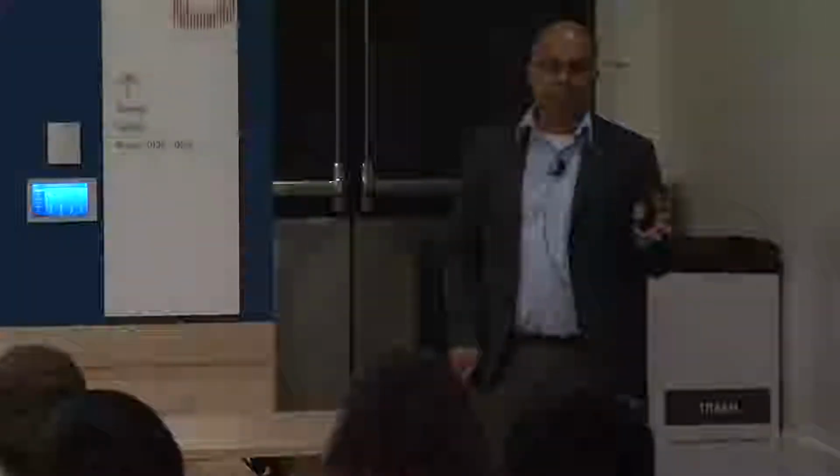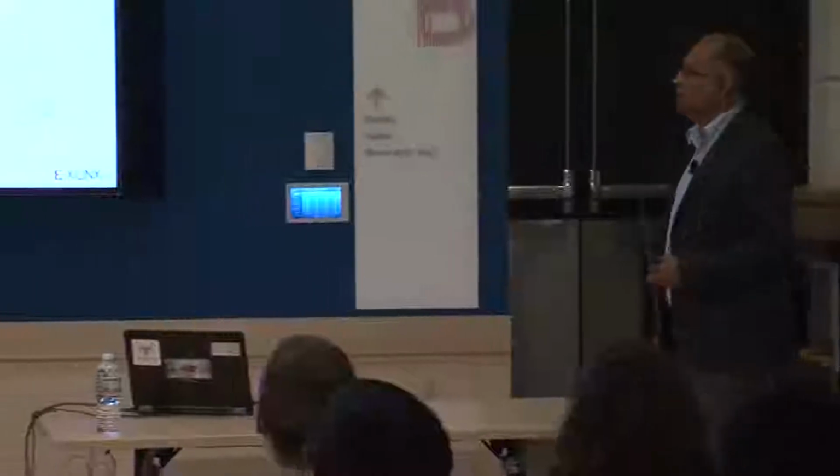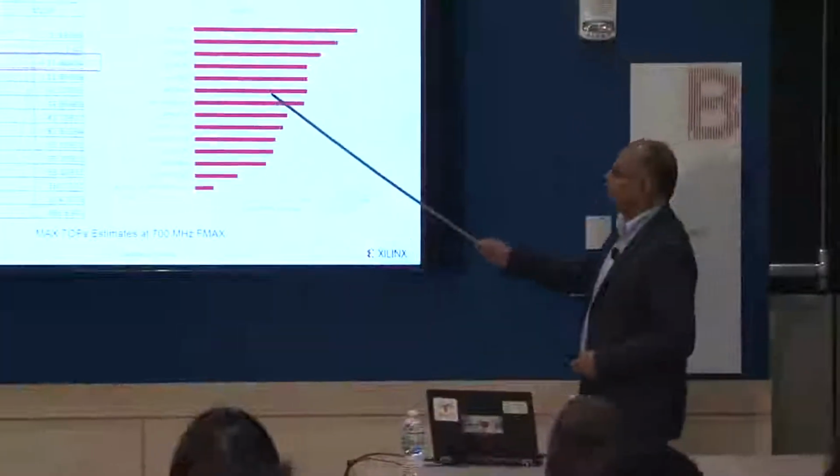But fundamentally, these systolic arrays work at the highest speed, and do not use any other FPGA logic. That is one of the things we try to use in our DNN architecture. Now, going beyond it, variable precision, compute density.